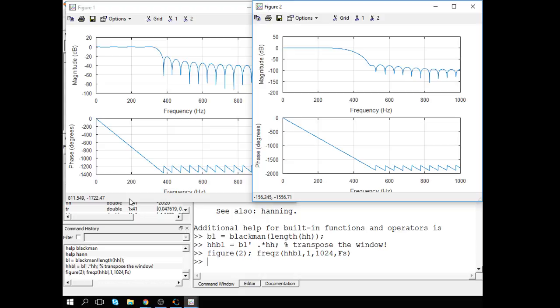Then we take a smoother window shape to reduce the effect of the high frequency edges, which gives better stop band attenuation at the cost of wider transition bandwidth, and finally you scale your window size to get the desired transition bandwidth. So there's not much to it, and that's the result.